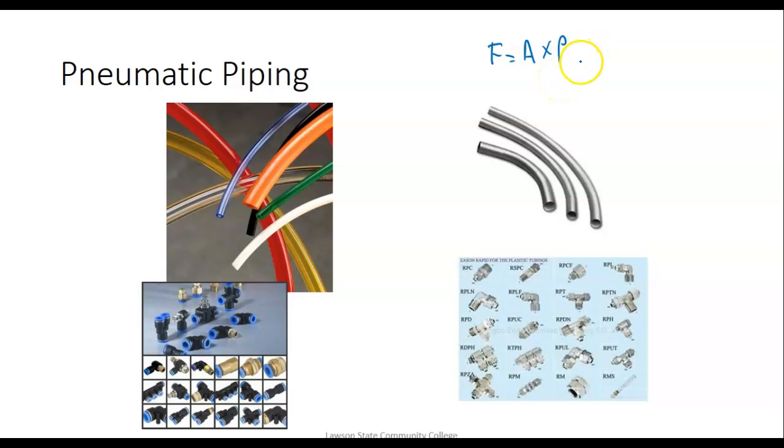So what this means is the higher the pressure, the smaller the area I'm pushing against to do the same amount of work. I think I told y'all the cylinders on our aircraft that move the big control surfaces, the ailerons and the elevators and all that other kind of stuff, were only about an inch wide, but they were using 3,000 psi pressure. So if you're using 3,000 psi against an area of 1 square inch, you could generate 3,000 pounds of force with only 1 square inch.